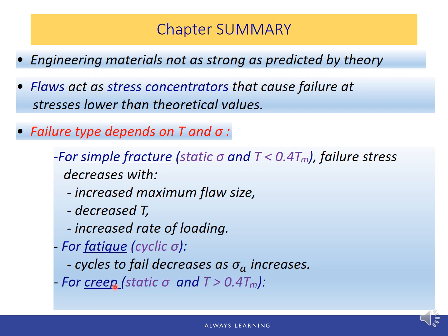Creep is also caused by static stress or constant stress at an elevated temperature. Usually this temperature is above 40% of the melting temperature. And the time to rupture, T sub r, decreases as the temperature and the applied stress increase.